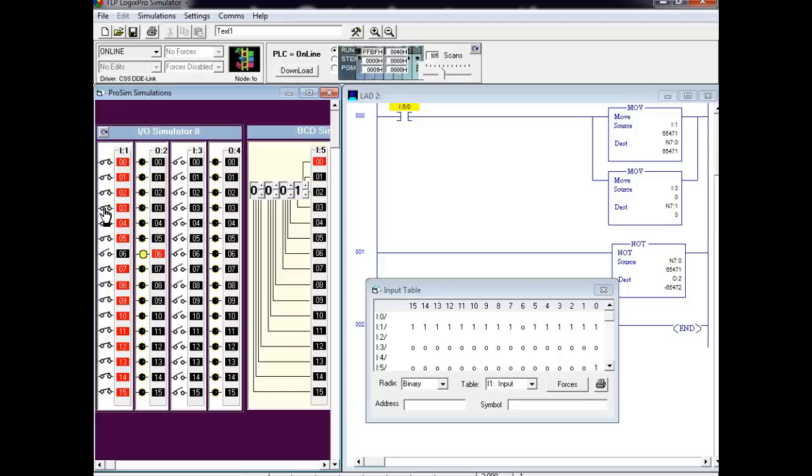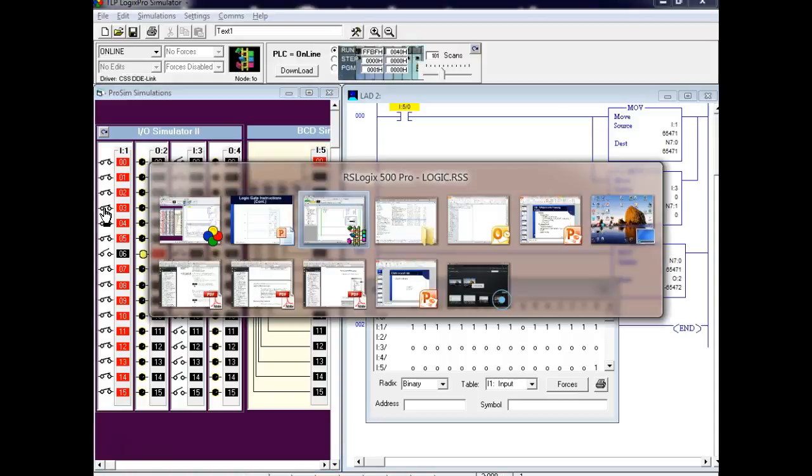We got power on it. Well, what does it provide me when it's closed? Does it provide me a ground or common, or does it provide me a 1, or does it give me a 0? Okay. So what are they hooked up, syncing or sourcing? If they was hooked up sourcing, I would get a 1 from them. Y'all understand? Yes or no? Y'all having a problem with that?